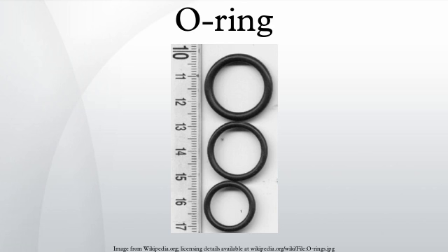When an O-ring is cooled below its Tg, it loses its elasticity and becomes brittle. More importantly, when an O-ring is cooled near, but not beyond, its Tg, the cold O-ring, once compressed, will take longer than normal to return to its original shape. O-rings work by creating positive pressure against a surface, thereby preventing leaks.